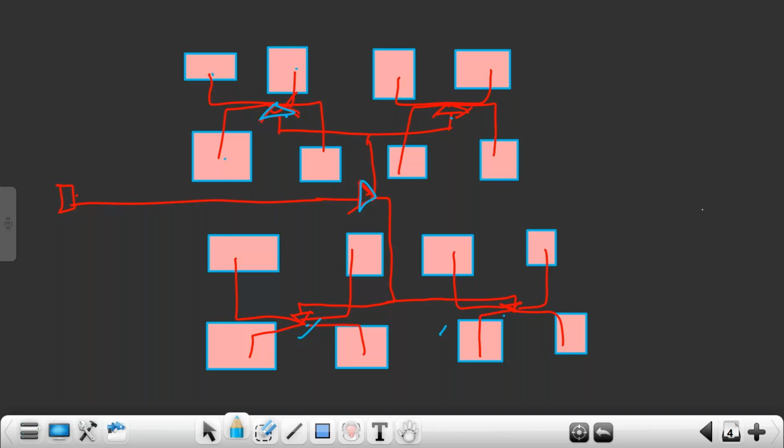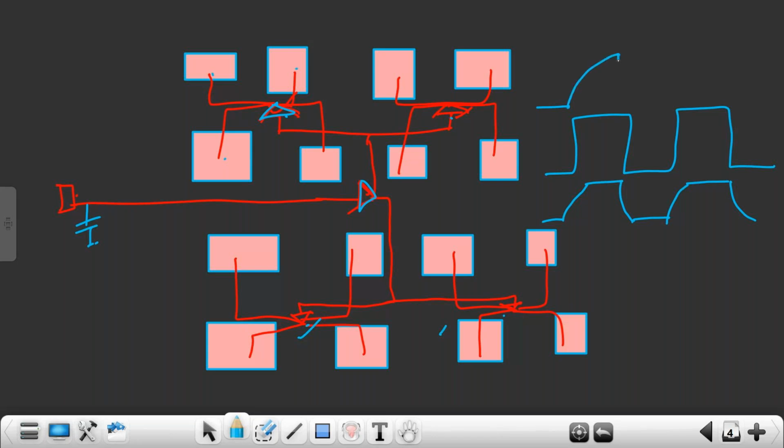If you build a tree, what happens? Then your clock will not degrade like that. So clock will become high. You will be having logic 1. Clock will become 0. You will get logic 0. Now shape is improved, right? Like this. Earlier, only one port was driving all the flip-flops. Because of that, load was very high. For that reason, it was taking more time to charge and more time to what? Discharge. So the clock shape itself is lost. Now you will get correct clock shape. So we have to build a clock tree like this.